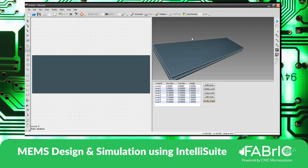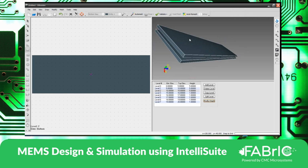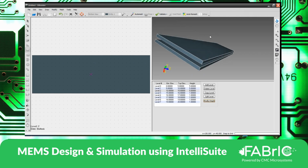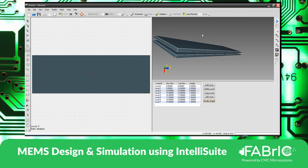Okay. So now I hinted that I wouldn't recommend using the 3D Builder module to start the geometry directly. The reason I told you is we are creating structures which have to be compatible with FEM, finite element methods. So now in the case that you are seeing, the two beams are not connected, or the two beams are not touching each other.